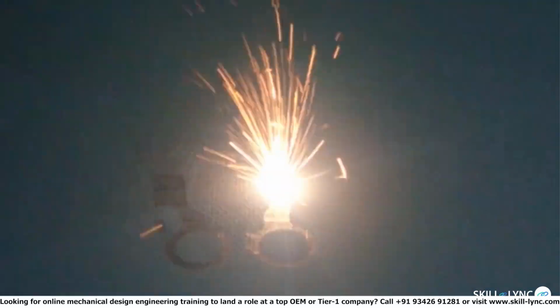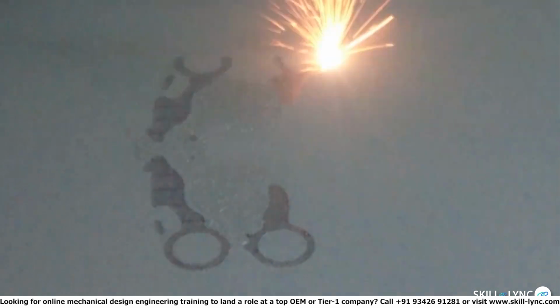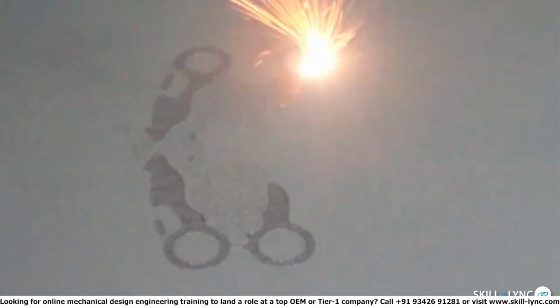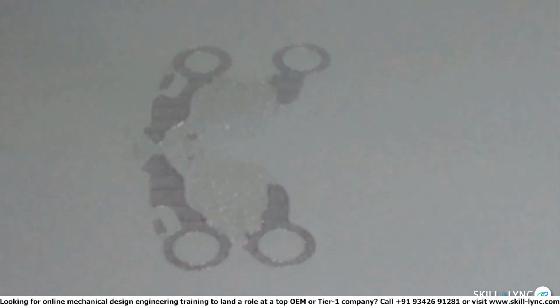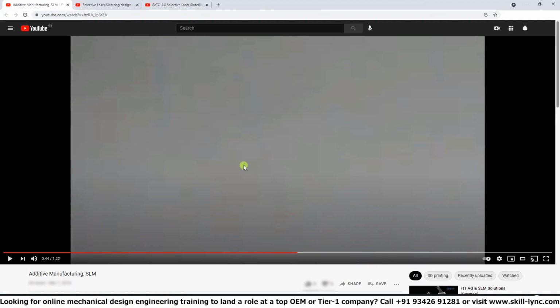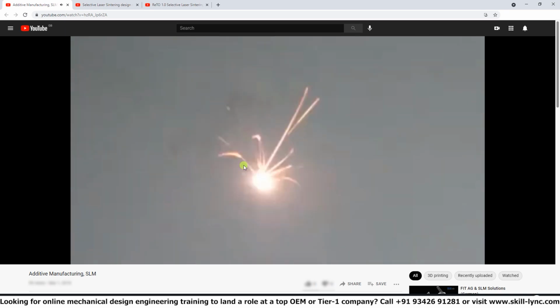as you can see it's coming back and forth right now, is depositing the next layer of powder on top. So you can see the previous cross-sectional area or layer that was just printed has now disappeared under that new additional layer of metal powder. And then the same process where the laser melts the next layer, so on and so forth. It gets repeated until the 3D printer itself goes through all of the layers of the model and finishes printing each one.